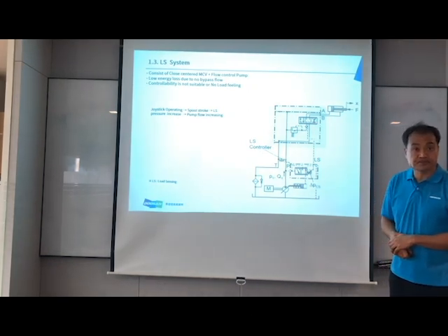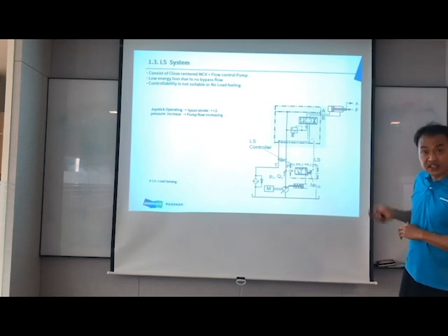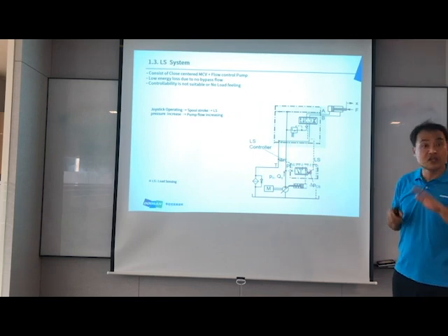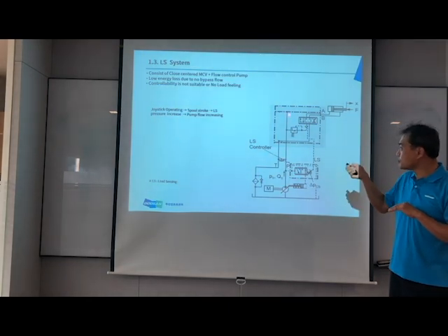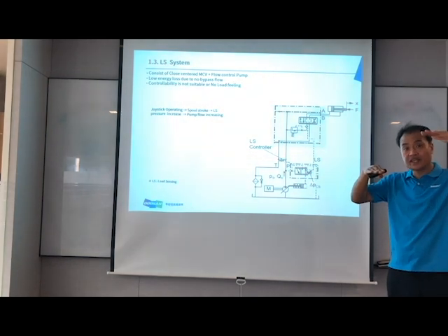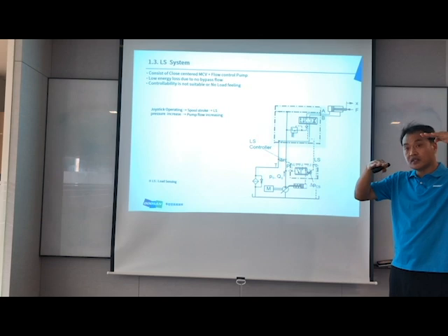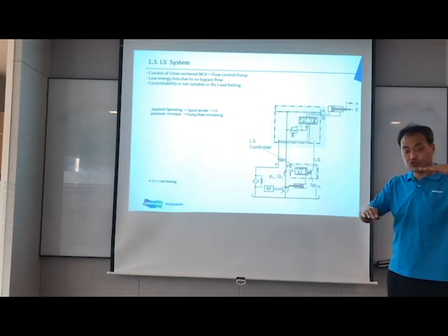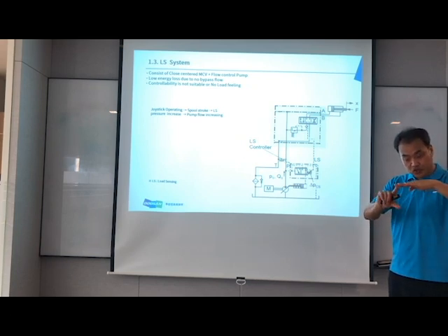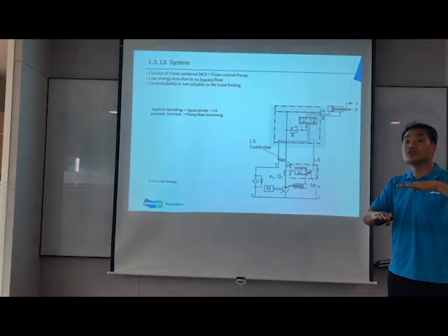So for example, the cylinder is working now, right? This pressure is, for example, 100 here. At that time, the pump makes this pressure 120 bar, 20 bar higher than the LS pressure. For example, if the cylinder LS pressure is going down, maybe to 80 bar, what about the pump? The pump makes the 20 bar gap, right? At that time, it reduces the pressure. How do we reduce the pressure? Reduce the flow. The pump reduces the flow, and at that time the pressure is reduced. That's why, once the 20 bar gap is reached, the reduce action will be stopped.